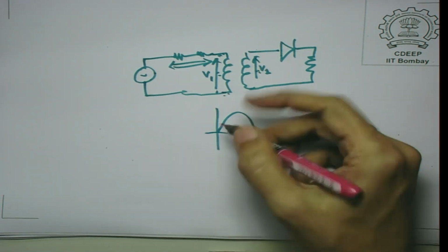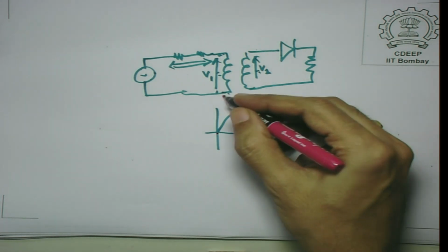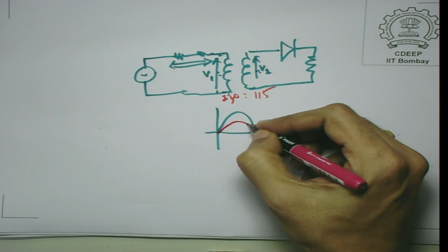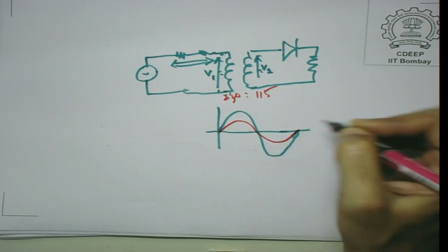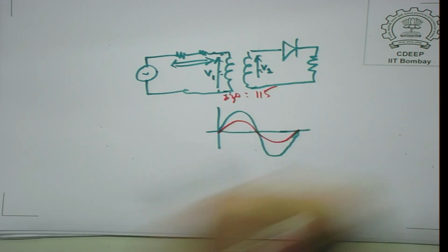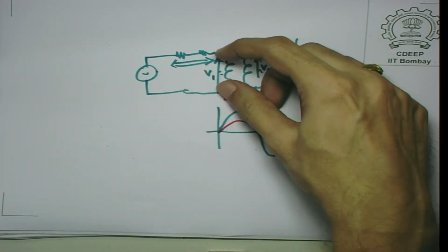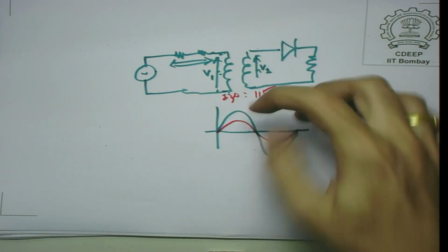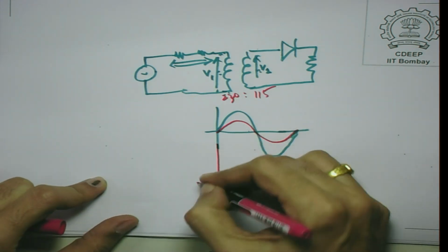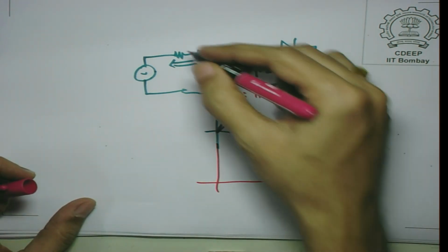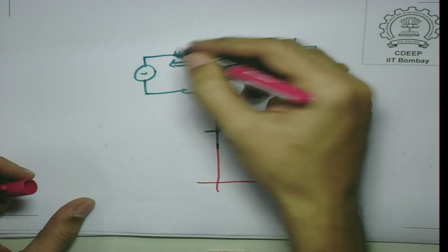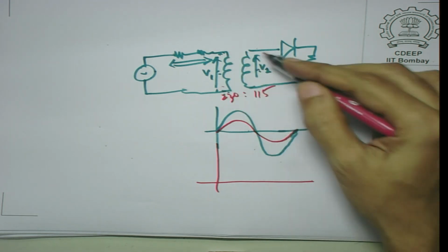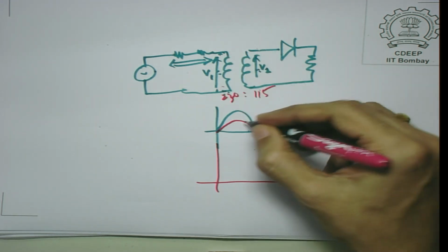So, one thing you can be reasonably sure of is that if you have a 230 to 115 volts transformer, the voltage on the primary and secondary is approximately this. Because the leakage parameters and resistances are small, you can be reasonably sure what the voltage across this winding is going to be, and therefore what the voltage across this winding, V2, is going to be.